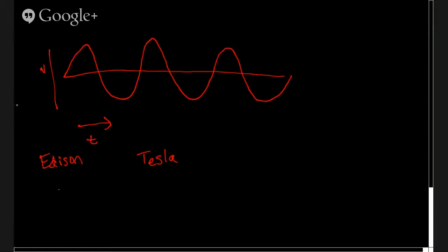This was a problem when we tried to invent the first telegraphs. We have miles and miles of wire, and of course, the longer a wire is, the more resistance you have, because we know that resistance is a function of the length of a wire and its cross-sectional area.